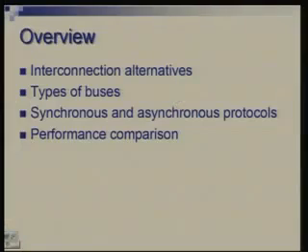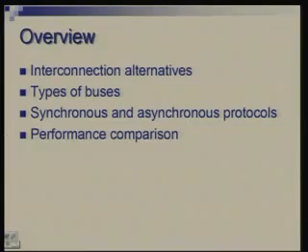It could be synchronous or asynchronous. Synchronous means it will be timed with a clock, and asynchronous means it will not be synchronized with any clock. There will be signals which will carry the event sequencing information. And we will then take some example trying to compare performance of two different protocols.